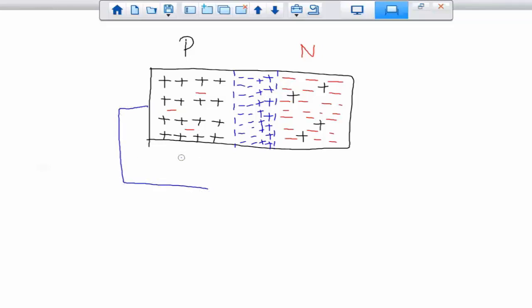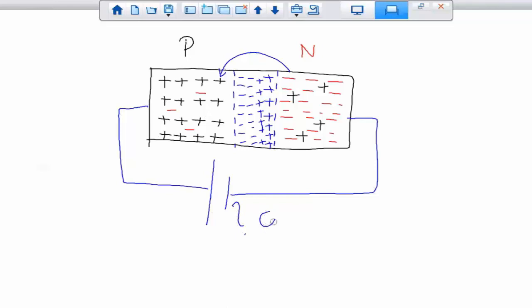So here you have an excess of electrons. So that side would be positive. This side would be negative. Again, if I want further more transfer across the depletion region, this voltage should be, if silicon based, at least 0.7 volts.